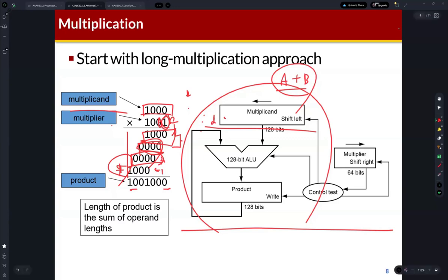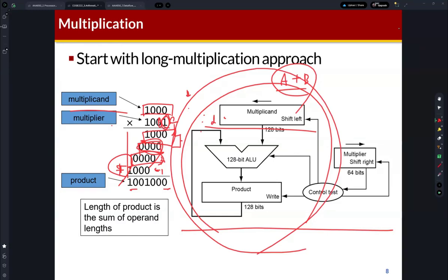Performance, right? Because we need to reduce the number of clock cycles for executing instructions. But if we implement the multiplier hardware like this, firstly generating the partial product, then performing the shift operation, and then accumulating it, then for example, for a 32-bit number, we need to repeat this operation 32 times, and it may take 32 cycles.